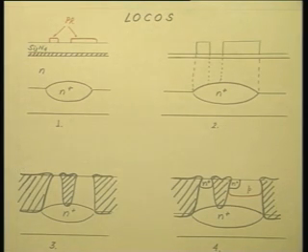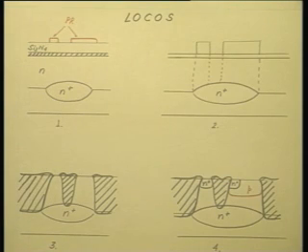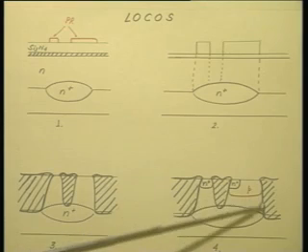Etching is done to realize only that much of recess, so that the top of the oxide comes only up to the surface. So, after this, when you carry out the oxidation, this is how the surface looks. You carry out the oxidation and then you remove silicon nitride from these remaining portions also. Okay. So, you see this is your N plus buried layer, and on top of that you have realized these two regions. Now, in one of these, now you carry out your base diffusion.